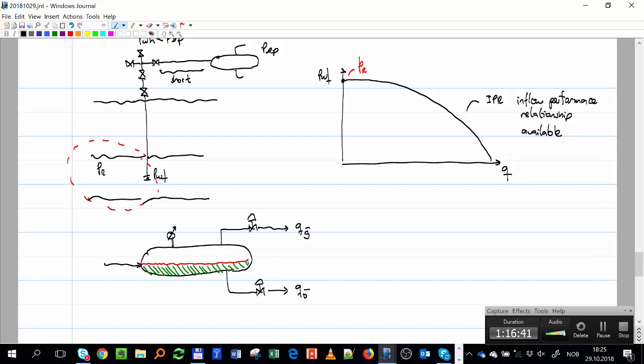One thing I have is this pressure, right? When that pressure starts to increase, it goes into a box, into a controller. Here I have a set point, the separator pressure set point. And the difference, if there is any, will tell me to open or close the valve. Now, what about the liquid? If a lot of liquid suddenly comes in...